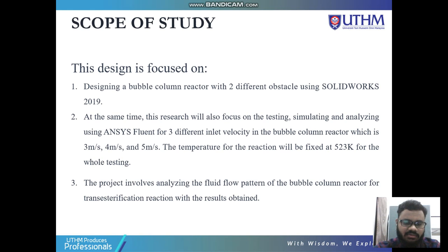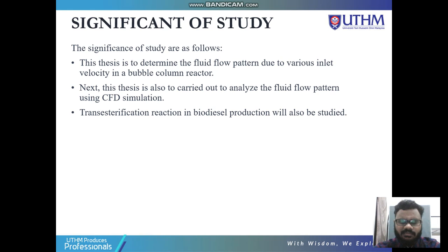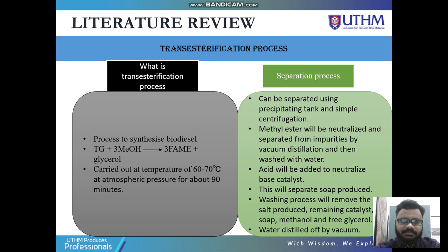Thirdly, the project involves analyzing the fluid flow pattern of the bubble column reactor for trans-esterification reaction with the results obtained. Okay, the significance of my study. This thesis is to determine the fluid flow pattern due to various inlet velocity in a bubble column reactor. Next, this thesis is also carried out to analyze the fluid flow pattern using CFD simulation. The trans-esterification reaction in biodiesel production will also be studied.